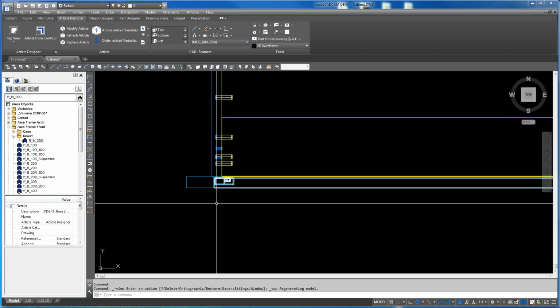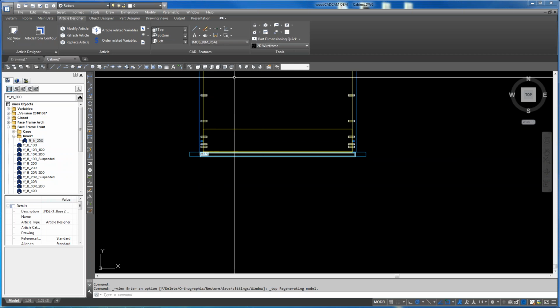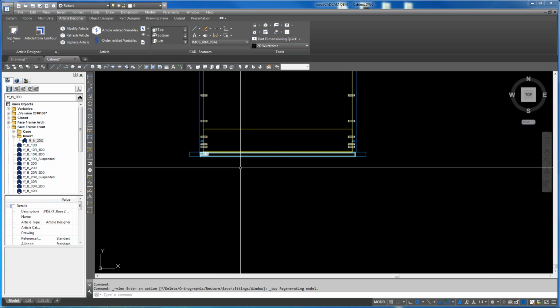I would actually use it around the box, because this frame, usually what we do is we have this frame around the whole box, and top and bottom, actually all around, it looks pretty much the same. So the guys in the shop would use a 3/4 scrap piece, make a tongue on it, screw it to the top of the box, and then the frame is attached to it. Yeah, I think I understand.